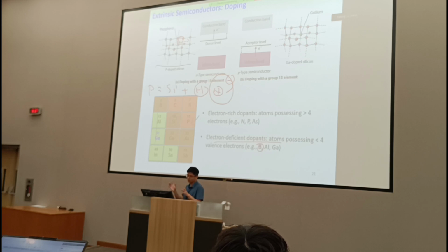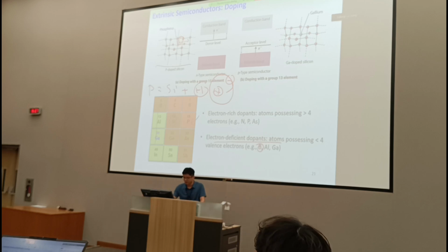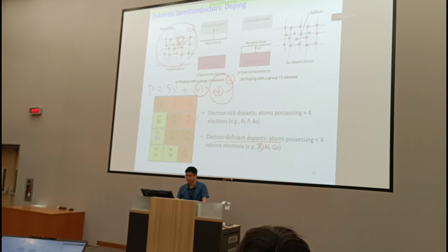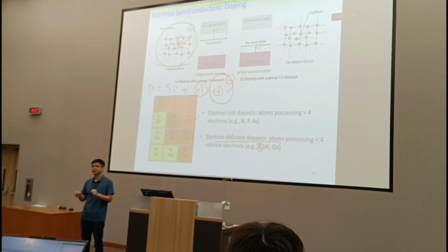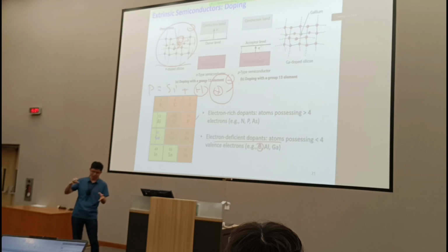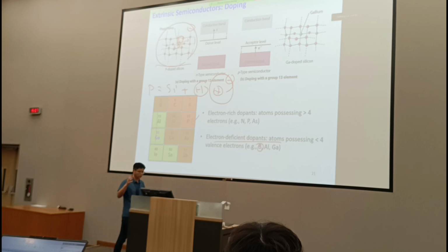That's why this donor state can be described by the quasi-hydrogen model, right? So you have the one positive charge here, and you have one electron orbiting around. Before ionization, this electron is not considered a free carrier, right? But inside the solid, this electron-hole attraction force is very small. Not like hydrogen. Hydrogen atoms, right? This one valence electron has a binding energy of 13.6 eV. It's very big. The thermal energy is so small. So that electron is tightly bound to the hydrogen atom.